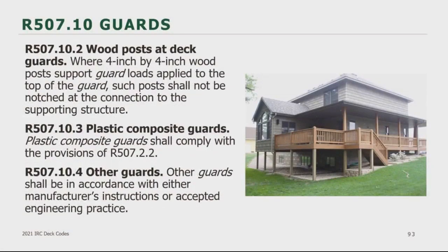R507.10.2 prevents you from notching a 4x4 post used as a guard post. R507.10.3 refers you back to R507.2.2 for plastic composite guards, and any other guard material you use needs to follow the manufacturer's installation instructions and, of course, any ES report in accordance with R507.10.4.